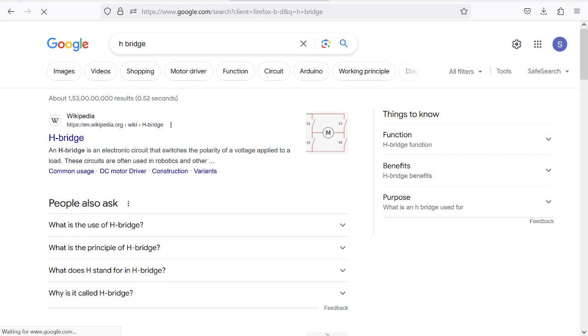But here the voltage is in the opposite direction, that's why the minus sign. If you want the average voltage, I have to add this up. So this will be D minus (1 minus D). This is the negative voltage amount, and this is the positive voltage, and we are taking the average. So this is the intuition behind this formula. If you open this bracket, you will get 2D minus 1.